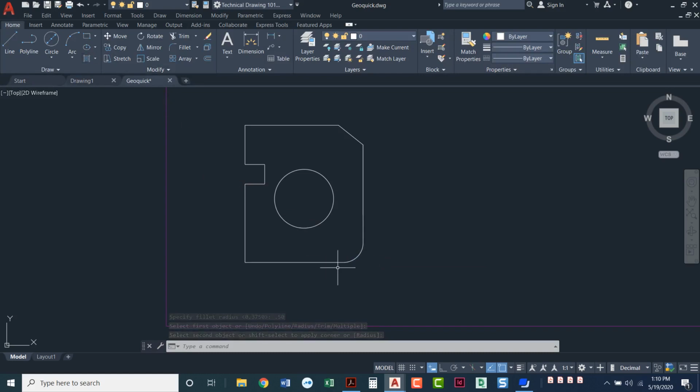Now, since that radius happened to be exactly where the center of that circle is, that center we did from that corner 0.50 over and up, I'll do the circle command, and this time if you hover next to that edge, I get a center O-snap. And now I can just type in my diameter, 0.375, enter. So that saves me a little extra time there. Realistically, that's how you would probably do it if you were trying to be efficient with your timing.